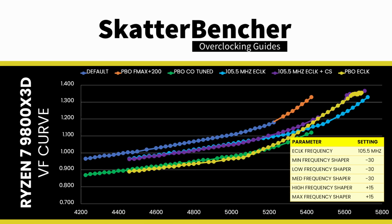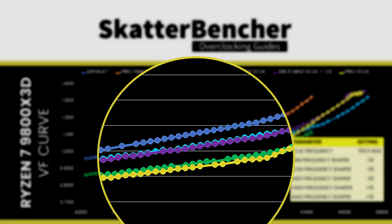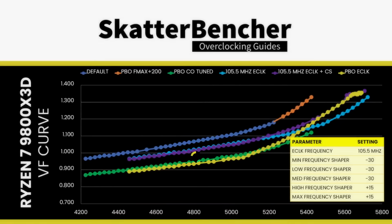Here's the resulting curve with an E-clock frequency of 105.5 MHz, a high max frequency curve shaper of +15, and a min, low, medium frequency curve shaper of -30. You can see that we effectively clawed back all the undervolting headroom up to about 5.2 GHz. Curve shaper is a very powerful tuning tool, and this example perfectly captures its core strength, adjusting the under and overvolt at different parts of the curve, which maximizes the frequency in light and heavy workloads.